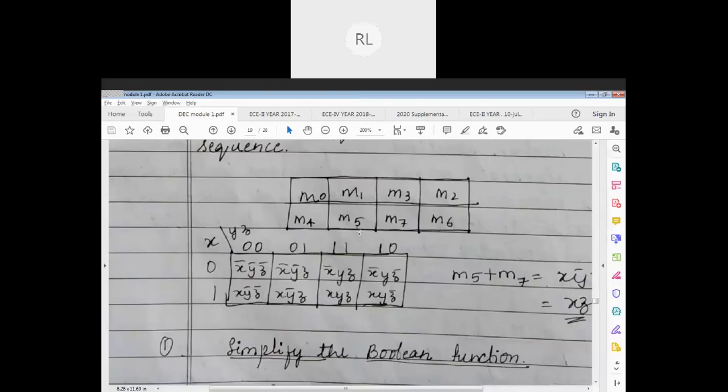So first I start off with 0, 1. I don't go with 2 here. Instead 2 is written here and then 3. Next 4, 5, not 6 here, but 6 is written this side and then 7. Now why do we do this? Because I just want one bit change in my binary.